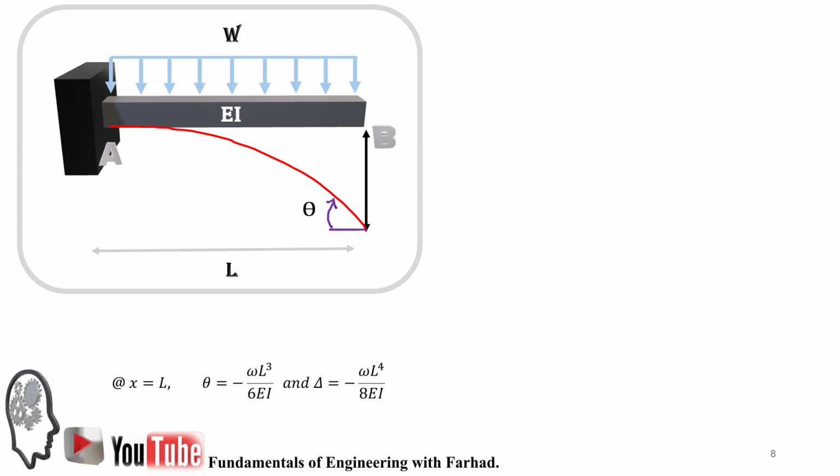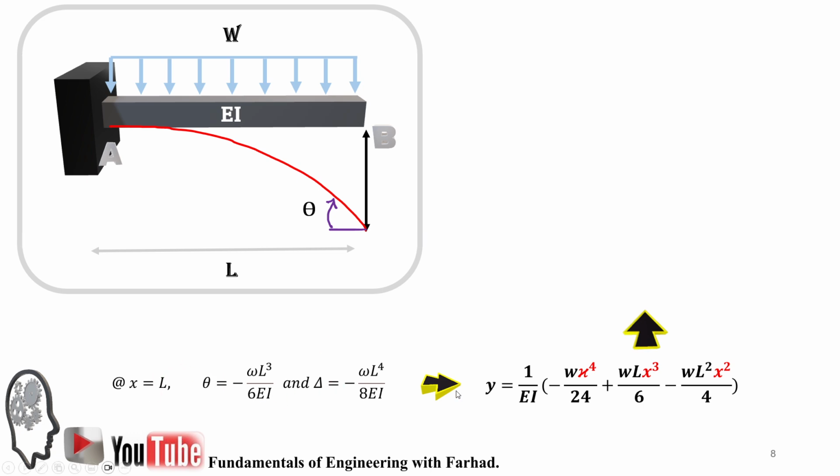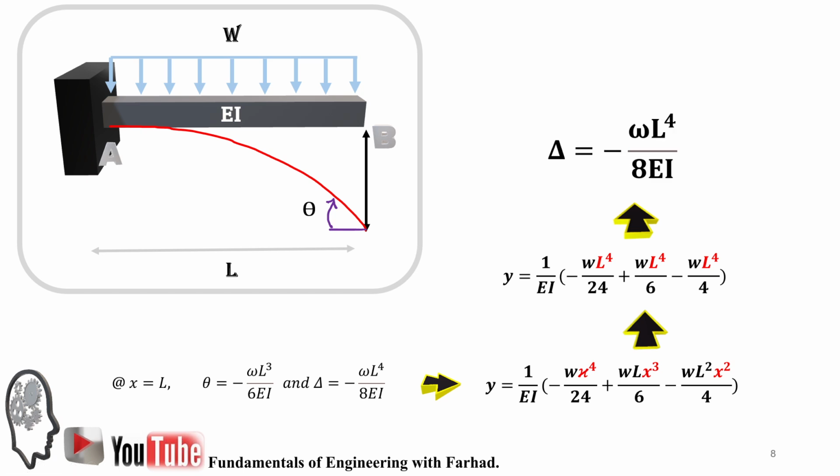Likewise, if we apply the other boundary condition at x equal to 0, theta is equal to this one. And also, if we calculate delta, let's replace all the x in the y function by the length L, because that's at x equal to L. If you do so, replacing all the x by L at the free end, it gives us delta equal to negative WL to the fourth over 8EI.